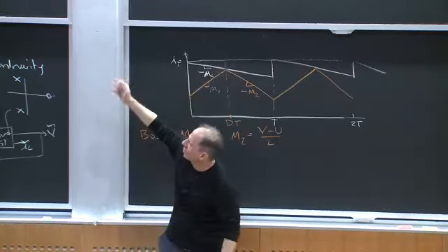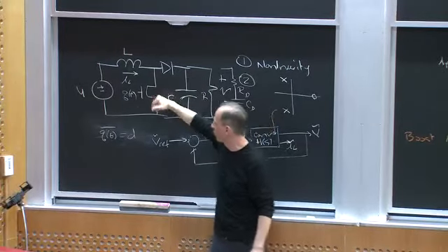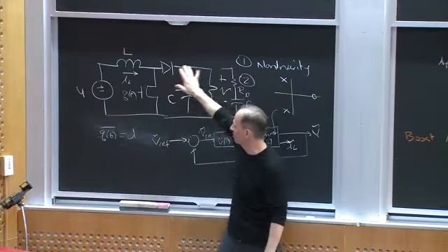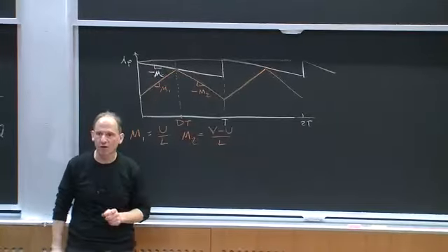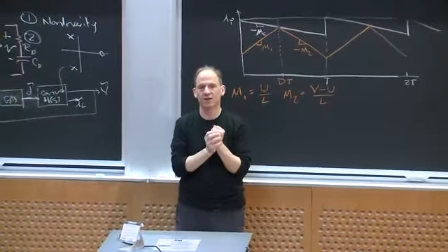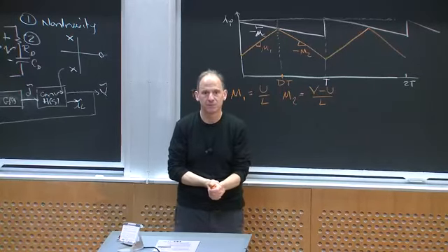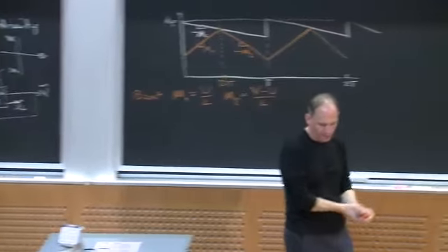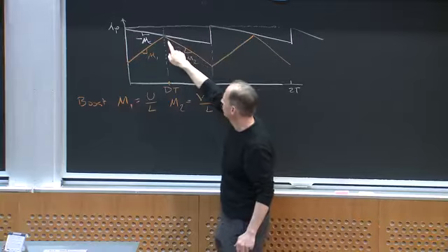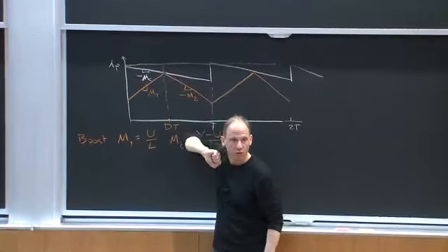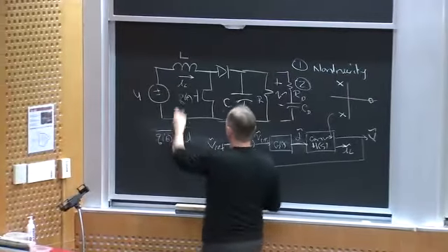Now, in a boost converter that's not quite true, because if I put a short circuit on the output, there's nothing I can do, since the switch won't control the inductor current. But as long as the output voltage is bigger than the input voltage, by having this peak current reference I can always limit the amount of current the converter is processing, and hence prevent it from overheating, for example. So essentially, this technique gives me cycle by cycle current control over the inductor current. Now I have to sense the inductor current, because I'm controlling IL here.